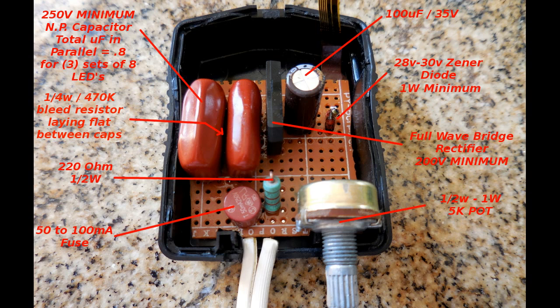This image here shows what it looks like inside my project box. You can see all the components, all clearly identified. One is hidden. There is a 1/4 watt 470K bleed resistor, which is laying flat between the two non-polar capacitors. In the very center, the long black strip sticking up is the full wave bridge rectifier. Be sure to use a 200 volt minimum when operating at 120 volts. When operating at 240 volts, make sure that is a 400 volt minimum.